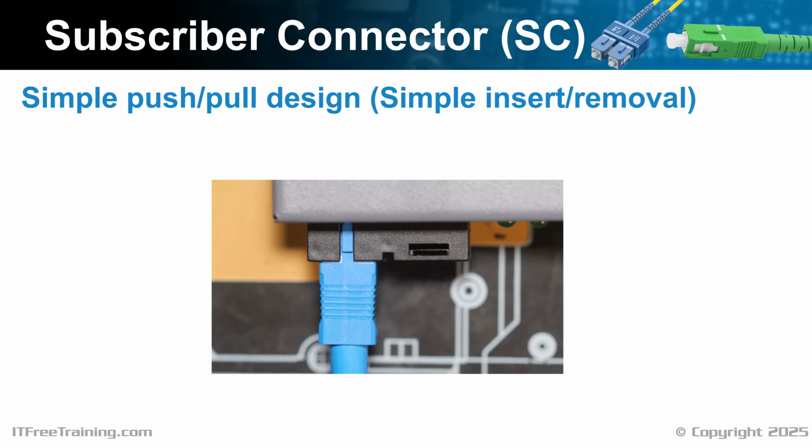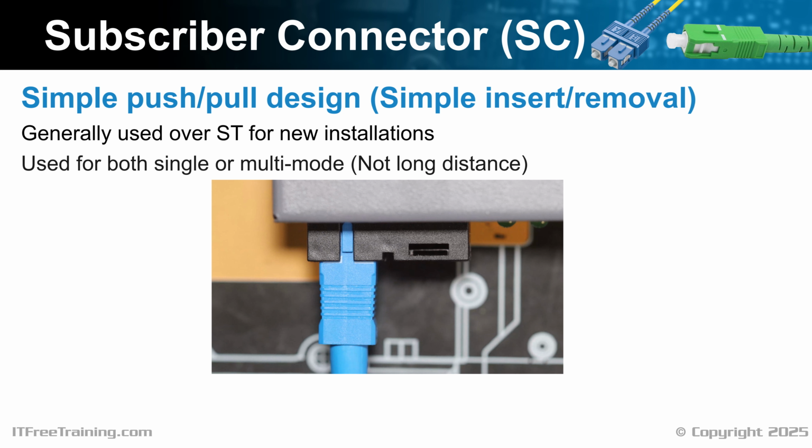The subscriber connector, or SC connector, features a user-friendly push-pull design for easy and secure cable connections. It is much easier to insert and remove than ST. Generally, this connector will be used over ST for new installations. It is used for both single-mode and multi-mode cables, but is not used for long distances.